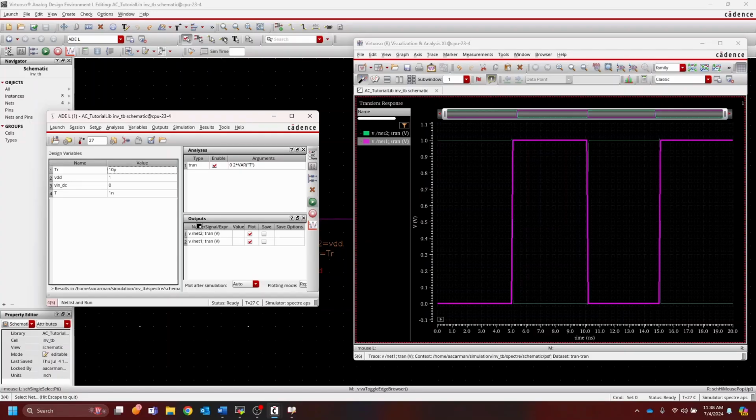Now, the benefit of this is that we don't have to go back into our schematic and change those parameters manually. We can just do it from the simulation window, and that prevents us from having to save and check, and do all that other really not fun stuff that can further complicate things. So defining things with variables makes it very easy to change later on in the future, which is fairly important. Because you don't want to have to go back and change too much stuff. You want to be able to just change it in one spot, and have those changes propagate throughout the entire design.